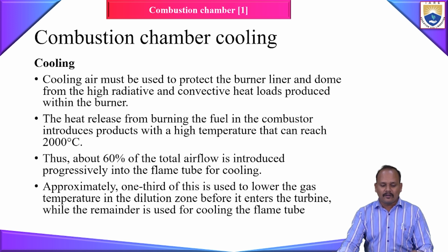So with high temperature you will have this creep problem. Even though the mechanical stresses acting on the combustion chamber are within the yield strength, because of the high temperature your material is going to elongate more and go to the plastic limits, which will cause permanent deformation. This continuous cycling or continuous creeping will result in failure of the material. Thus we have to prevent this creep problem. How do I prevent it? By cooling down the gas, because creep is directly proportional to the temperature of the gas. The higher the temperature, the higher the creep problem.